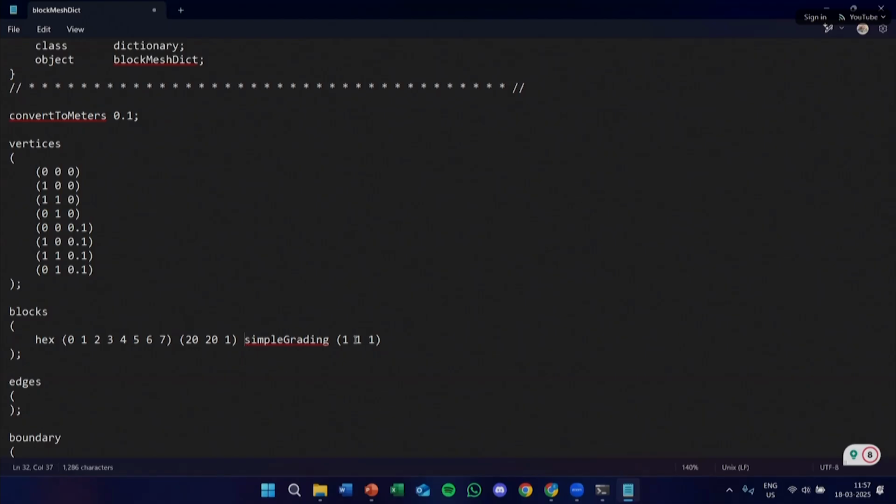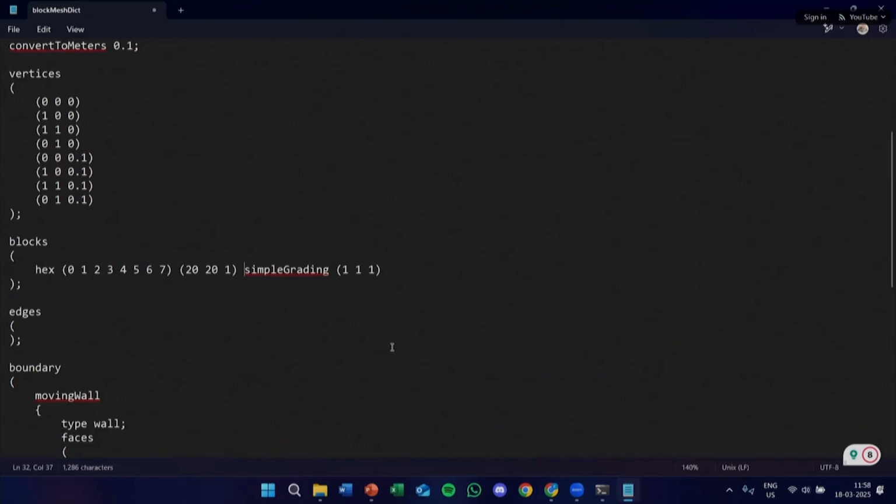Hello, Ravi. I just wanted to ask one thing. Here we have made the control volume hexagonal, something like a cuboid, right? Had we wanted this to be of some cylindrical shape, what would have been the command for that? Okay. So you would specify your front plane, and basically you would go in your X and Y direction, make a circle, and then extrude it in your Z direction.